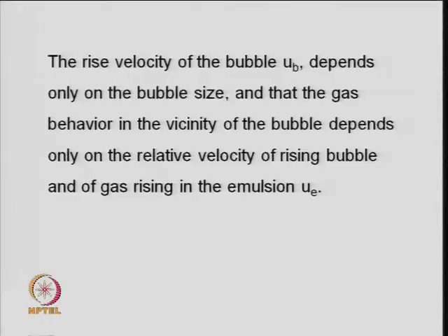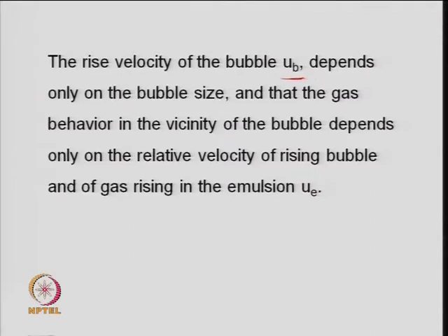It says that the rise velocity of the bubble, which I am now defining as u b, has a unit of meter per second. This will depend on the bubble size. Using the hydrodynamic correlations, the mass balance and the force balance equation, one can calculate this. The bubble size is very important because it will decide the rise velocity of the bubble.